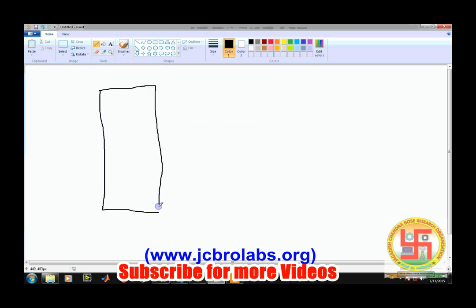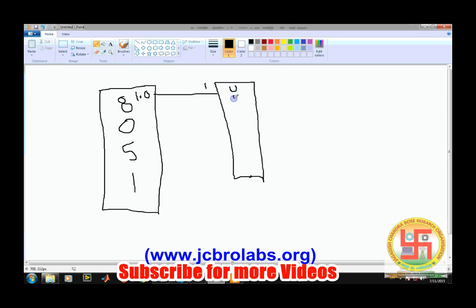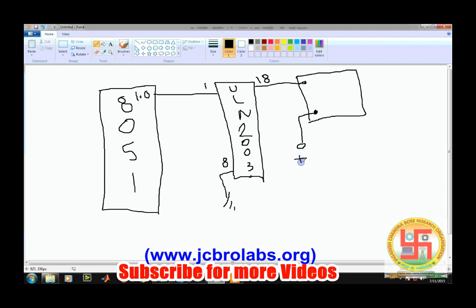So this will be our circuit diagram which we will be implementing. We have this 8051 microcontroller, and we have connected pin 1.0, port 1 pin 0, to pin 1 of this ULN2003, and pin number 8 of this ULN2003 is grounded, and then this is pin number 16 of ULN2003. So we are using a relay, so we will make the connections like the relay which we have, and we have connected this to a plus 12 volt power supply.